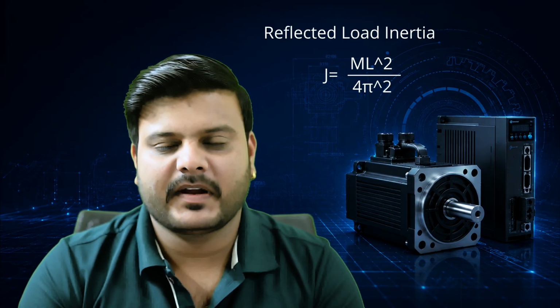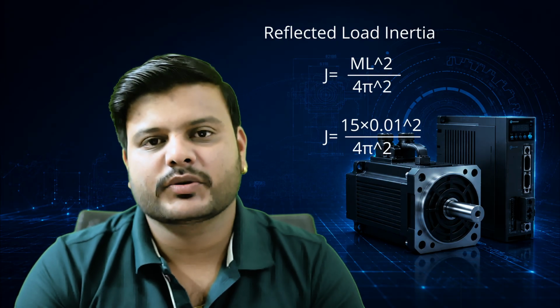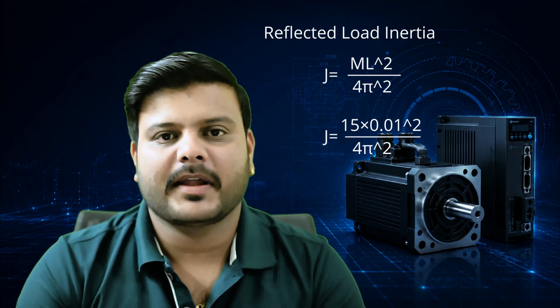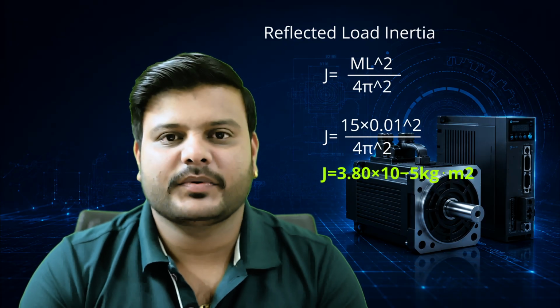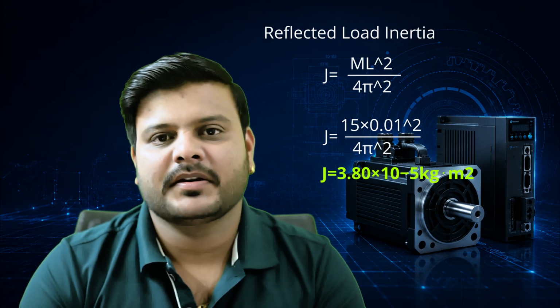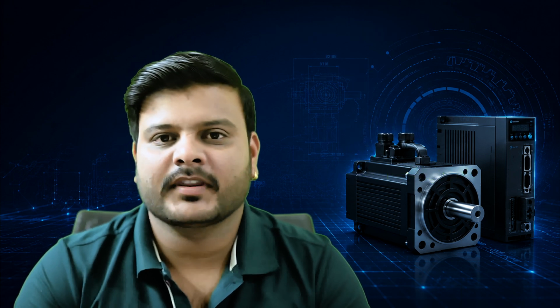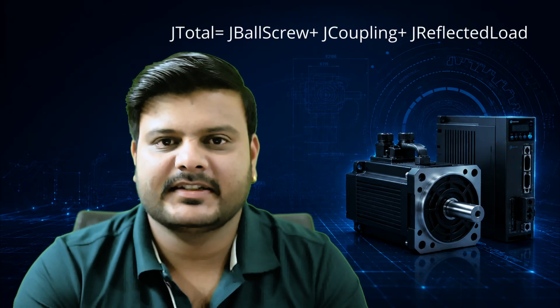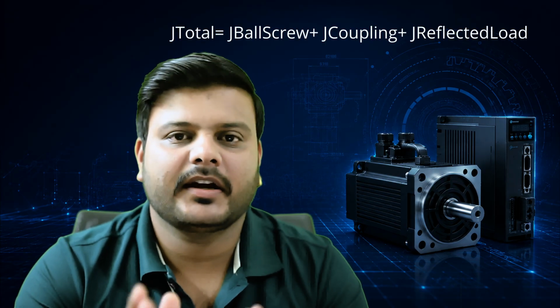Substitute the values in the formula. J is equal to 15 multiplied by 0.01 square divided by 4 multiplied by pi square. So we get a reflected load inertia J is equal to 3.80 into 10 raised to minus 5 kg meter square. After calculating reflected load inertia, we notice that the moving mass contributes more inertia than the ball screw inertia itself. So our total load inertia J is equal to ball screw inertia plus coupling inertia plus reflected load inertia.